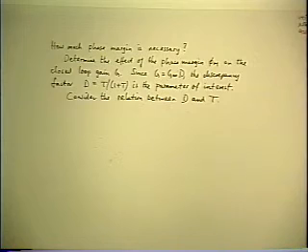Now, even that isn't the only question, because what really matters is not the nominal shape of D. What really matters is worst case shape of D, because you have a tolerance on the specification and you have tolerances on the components that you're going to build into your system. So what really matters is that you have to meet the specification tolerance under the worst case combination of component tolerances. So what matters is the minimum phase margin under worst case conditions.